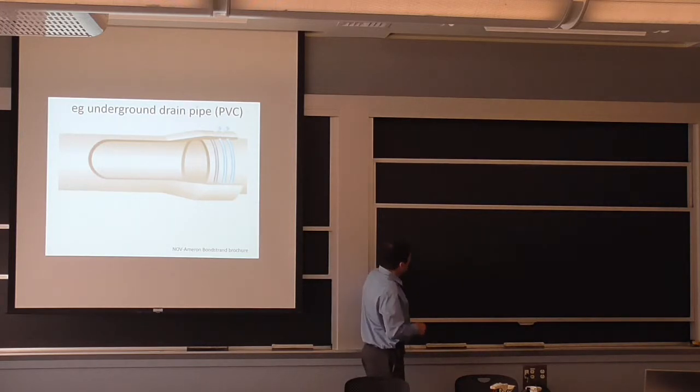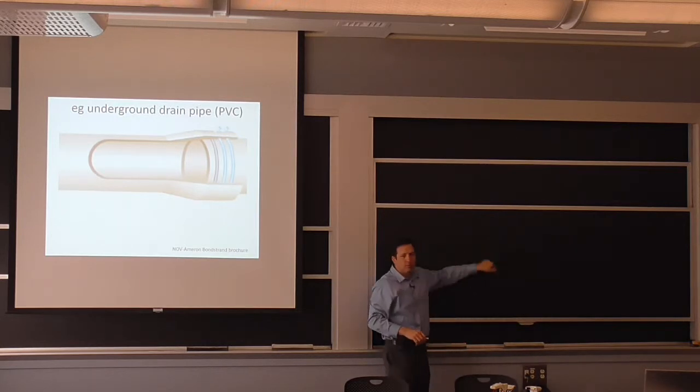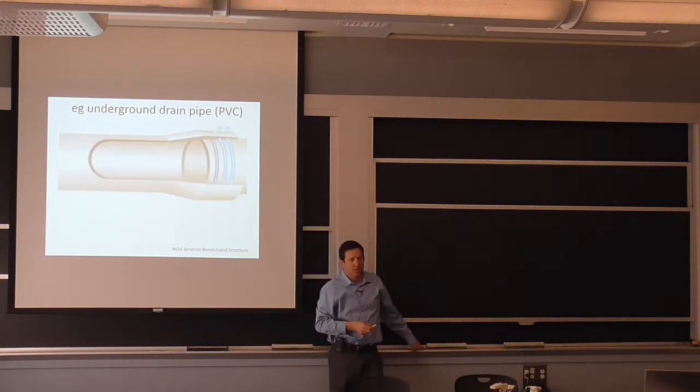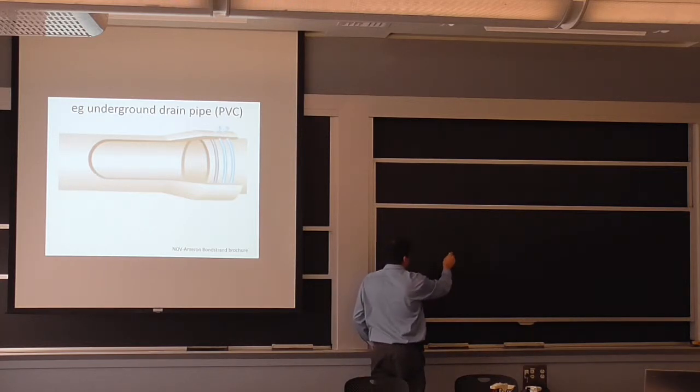And the implication here is if this little lateral is short and you try to move 4 inches, you get a lot of bending stresses at that transition, at those T's or Y's or whatever the exact design is. So there are two ways around this. One is you can put an expansion joint on the main line here, and there are different kinds.